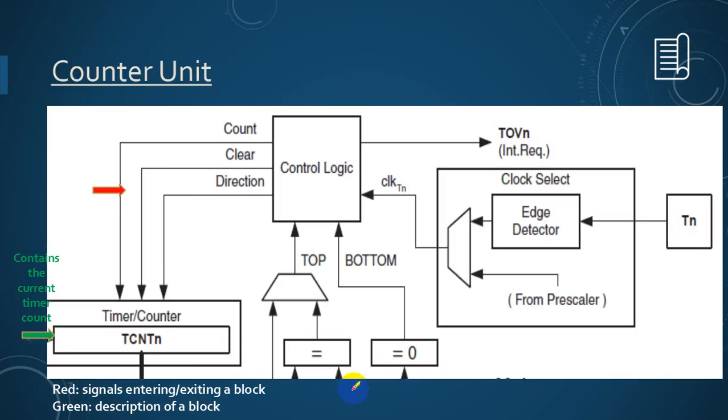So this is the counter unit. You will get the entire operational view of the counter unit, step by step. So I will go step by step, okay? And each step will tell you what is the sequence of operation. So first step, external clock source. Most commonly it is 16 megahertz for the Arduino. ATmega328P processor for the Arduino board, 16 megahertz.